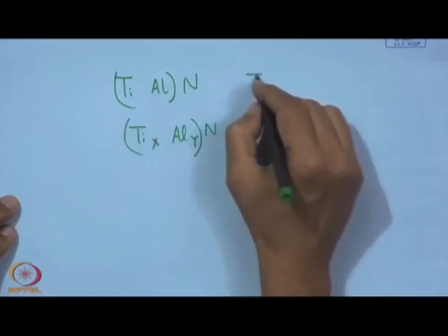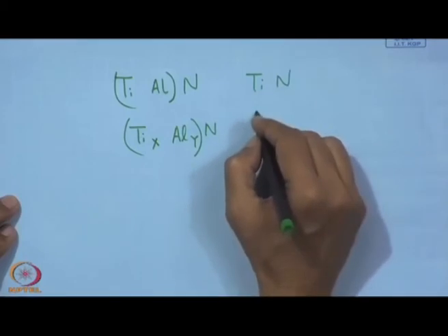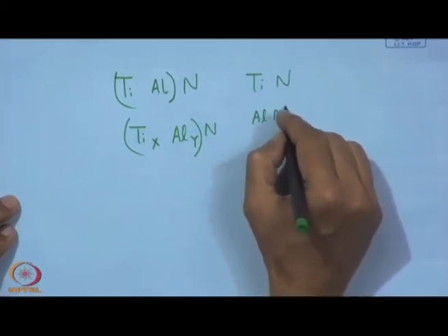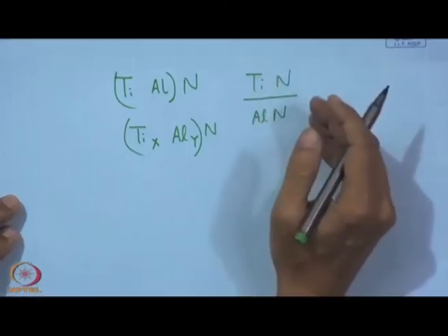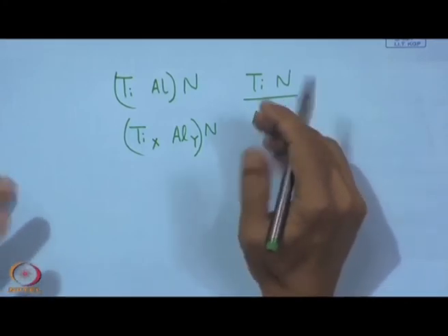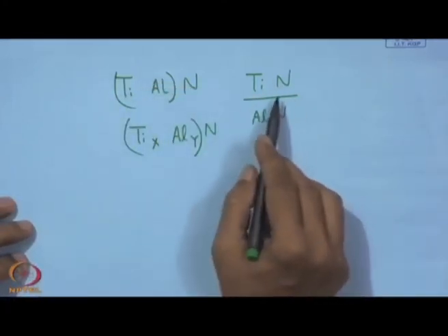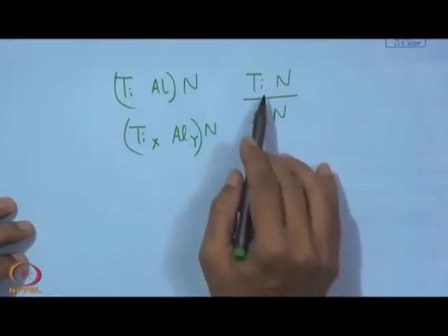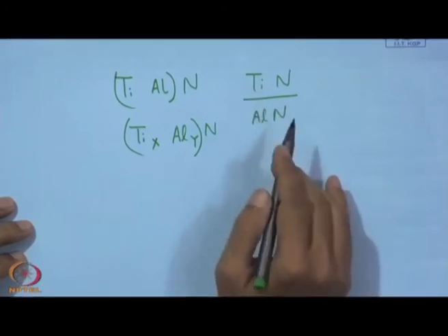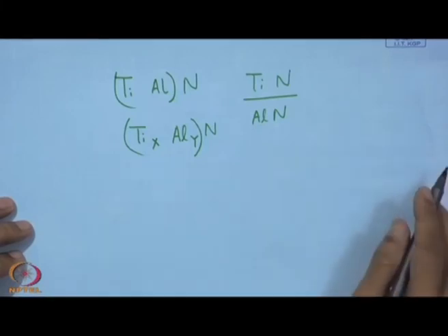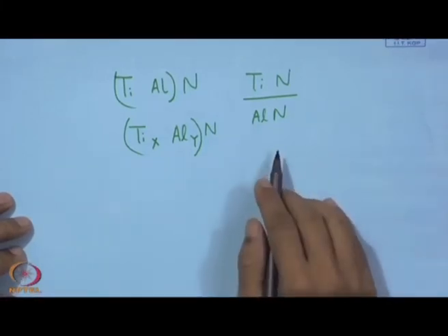Now, in fact, if we look into the equilibrium diagram of TiN and TiAlN, then we see that there is a solubility gap, so they cannot be put into one club like that. Normally they are not soluble in each other. That is in the normal equilibrium state. However, if we can change the pressure, temperature, composition combination during the processing, it can have a metastable state.